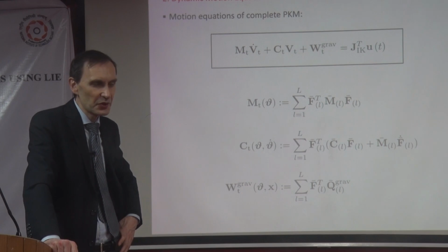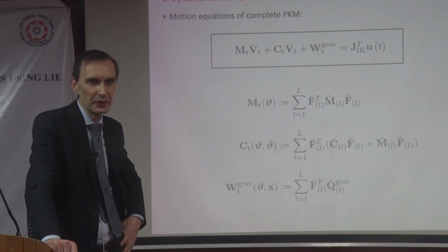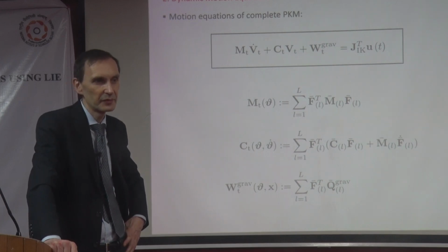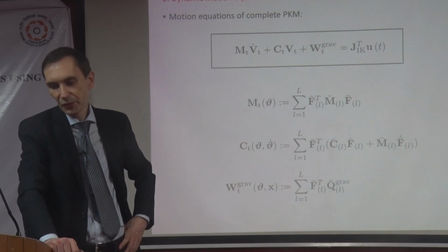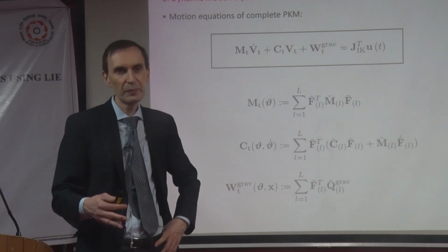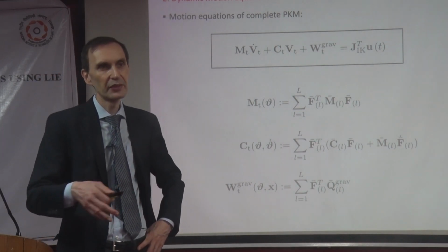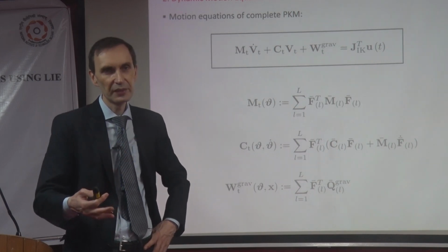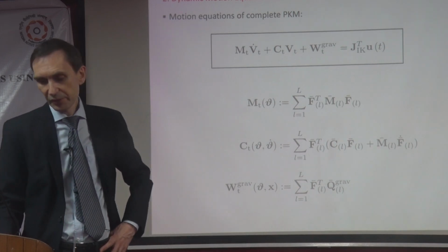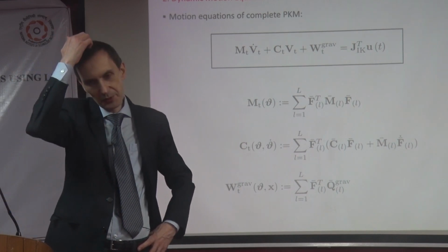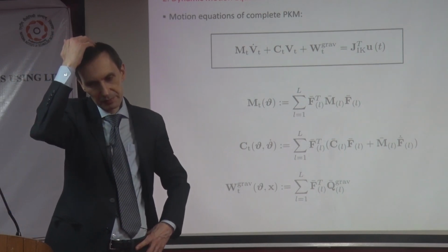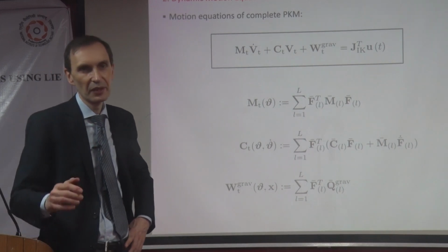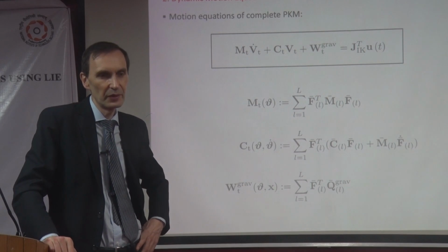Well, there's lots of research going on. Essentially, you have to construct your own controller. The standard approach, the easiest way, is to find a Lyapunov stable control system. So you find your Lyapunov function, and then you design your controller, and you show it is stable at least. But then you have to tune it. For flying systems, there are different approaches and different opinions on which one is the best. So you have to look at your system.